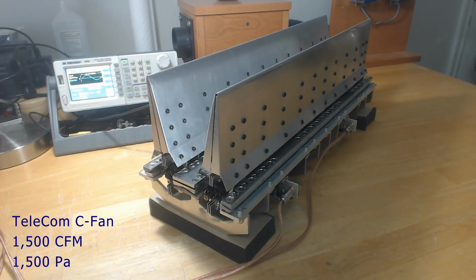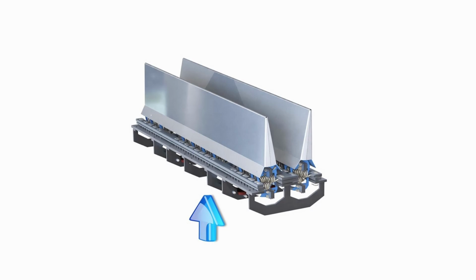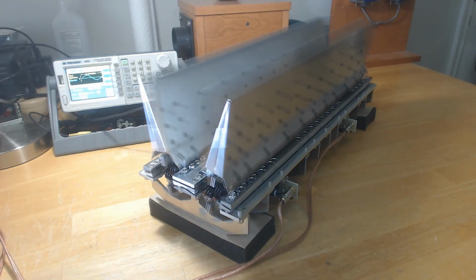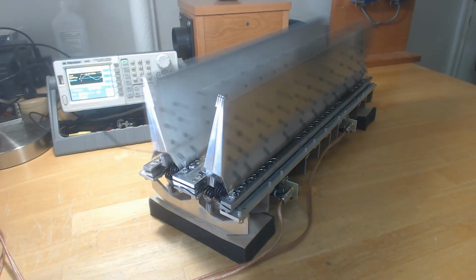C-fans solved the premature failure problem by replacing rotary bearings with planar fan blades that pivot on infinite life springs. Air enters from the bottom of the fan and exits axially from the top. Air is forced through the fan primarily by centrifugal acceleration along the surface of the blade, and then leaves the blade at its tip. Higher pressures are synergistically created using the C-fan's mechanically reciprocating volume and a time-varying exit area.